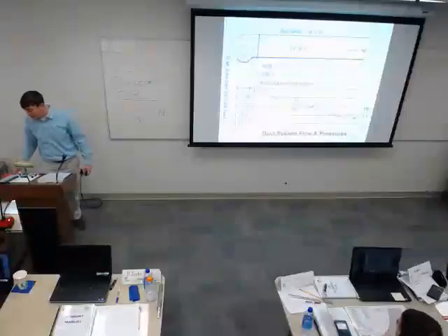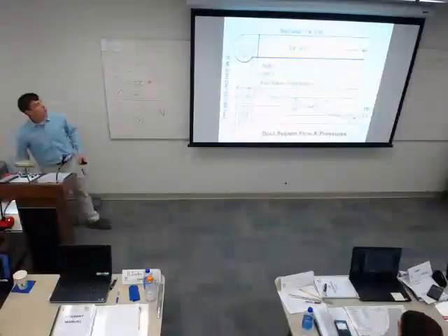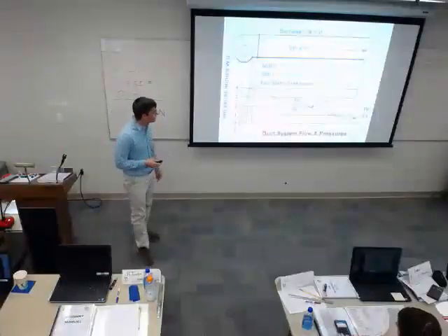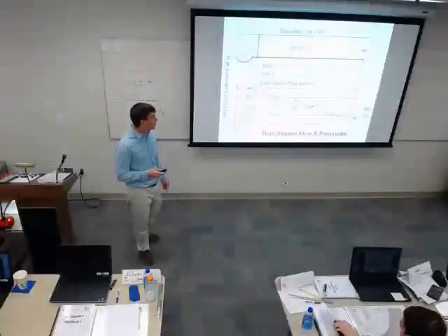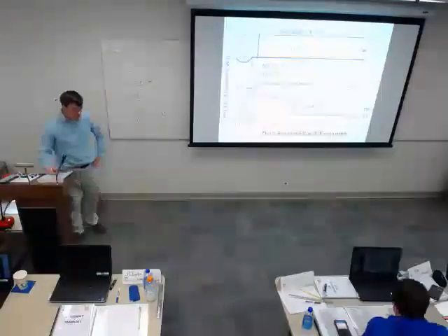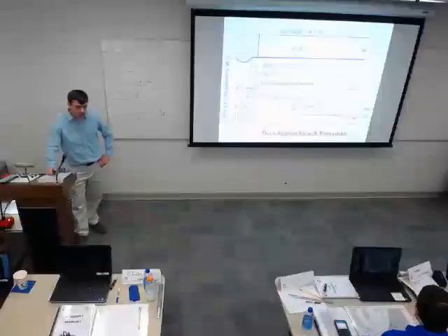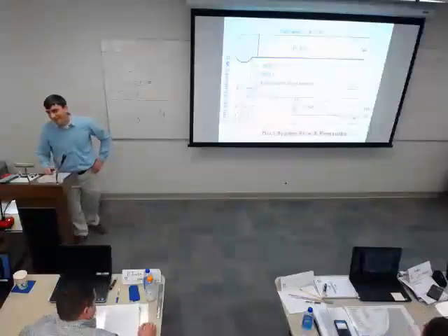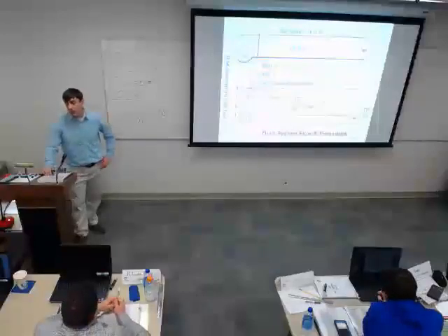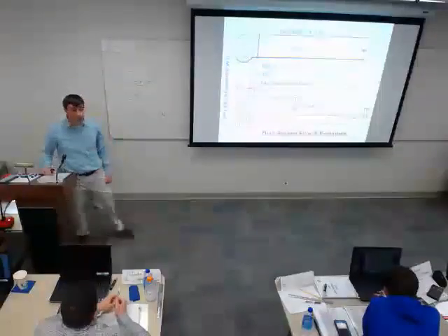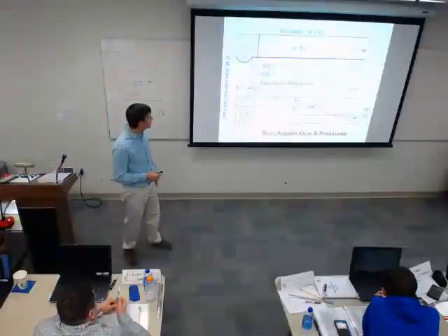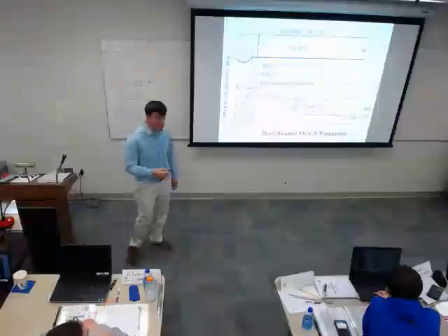No, I'm saying feet per minute, the velocity. It spits out velocity. Oh no, I'm sorry. Yeah, I misunderstood. Like it calculates the velocity on its own. I'm just wondering if you've seen anything where it's just putting out the pressure, not the velocity. You can just program a chip to do that. That's easy. Correct. Yes, as long as it's compensating for density, which all the newer stuff pretty much does. Sorry, I misunderstood you. Any other questions on this slide?